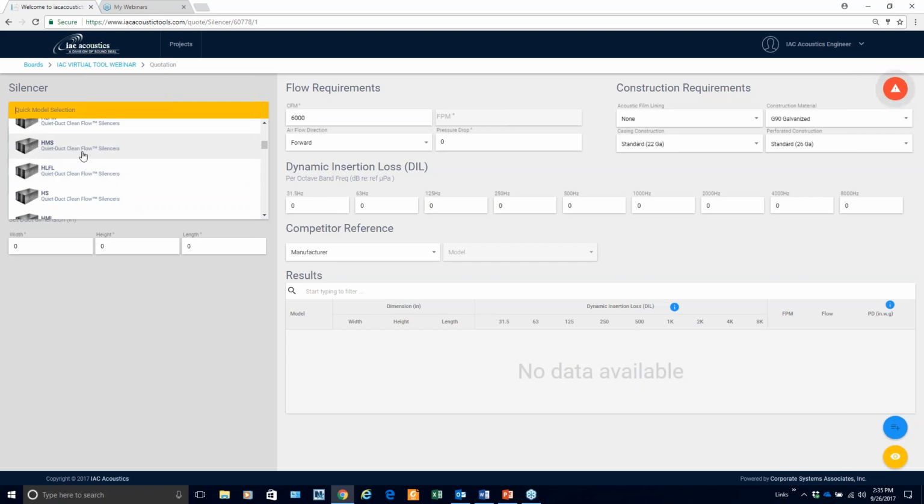Again, the H stands for hospital grade. That incorporates the polyethylene liner and the standoff in with the silencer. You then have the ultra green type silencers that have the anti-mold, anti-mildew, antifungal type infill. It is not fiberglass. It is actually 100% environmental cotton, kind of like the jean material that we wear. Then we have our ultra low grade.